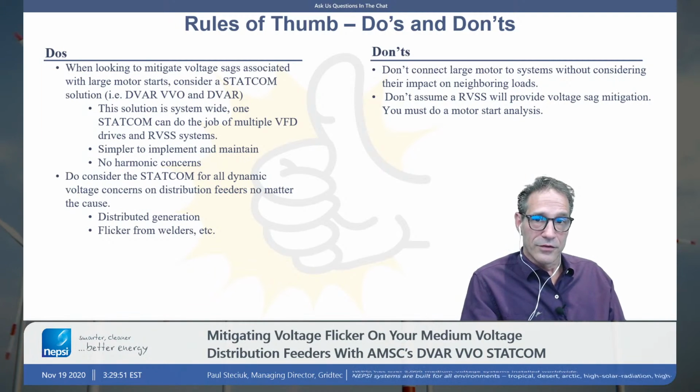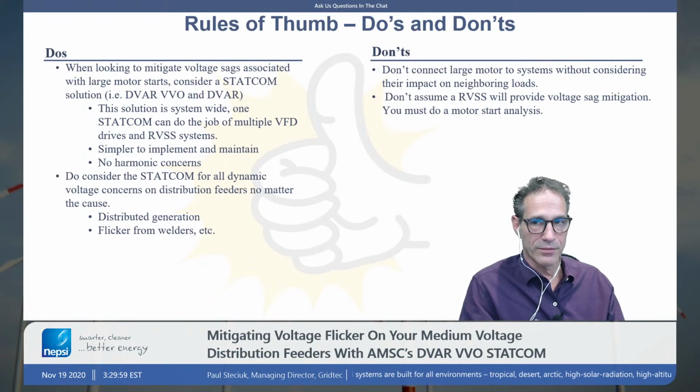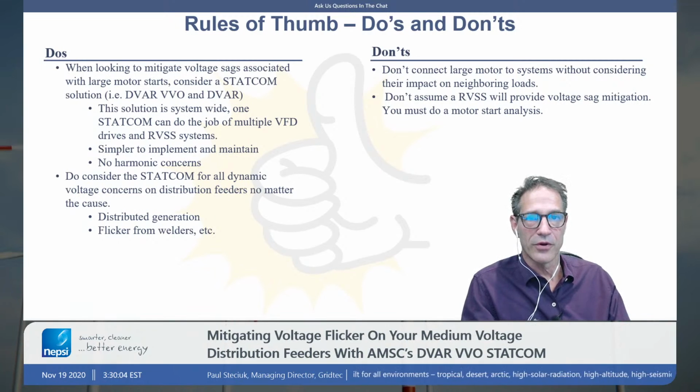So do consider the STATCOM for all dynamic voltage considerations. They would include distributed generation and also flicker from welder applications. So other places where you might want to think about using this VVO product.